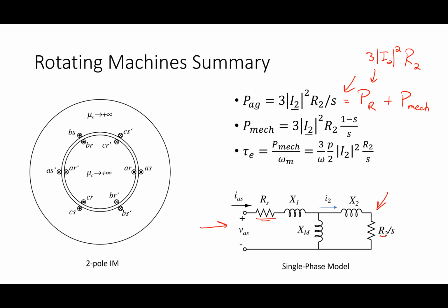Let me just shift over real quick to this picture. I wanted to show you guys what an actual rotor looks like. I brought in the stator before, the induction machine, but just to be clear, this is a rotor on, I want to say, a 1.5 horsepower, maybe a 2 horsepower motor. What you can see here, if you look carefully, are laminations of iron. It's got sheets of iron for the rotor. And then what you see here, these bars, is aluminum. And if I look through, I'm not sure how well you guys are going to be able to see it.